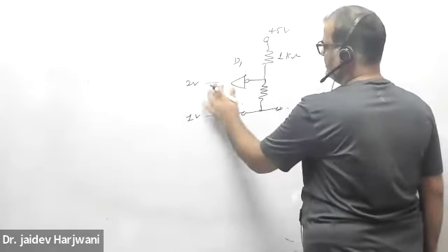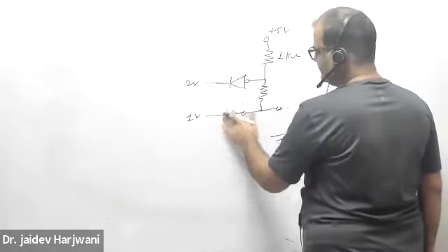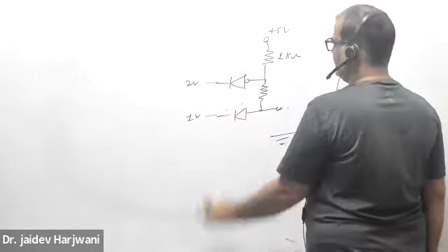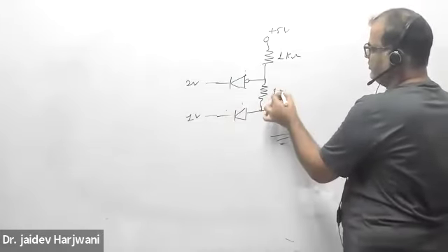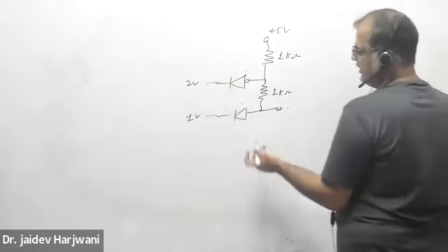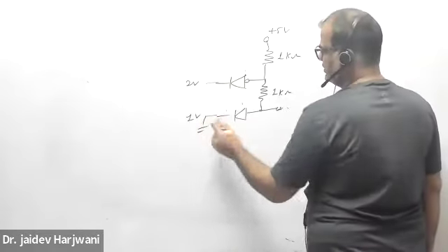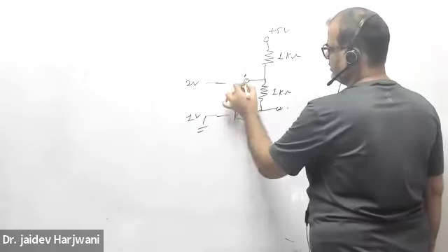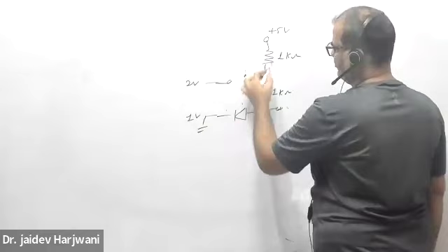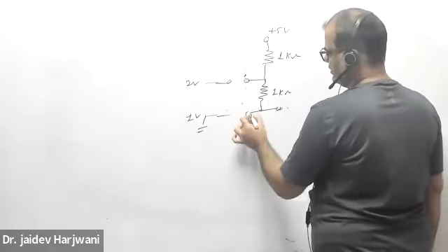And if this diode is there, then this becomes a different thing. Okay, say this is also 1 kilo ohm. Now you have to again find the open circuit voltages across. Say this is open. Okay, if this is open, so no current is flowing here, and this is also open.